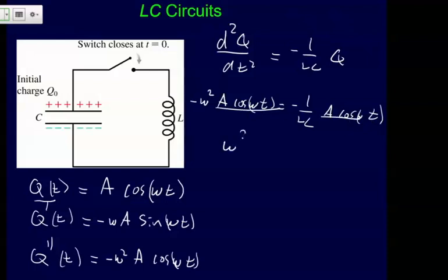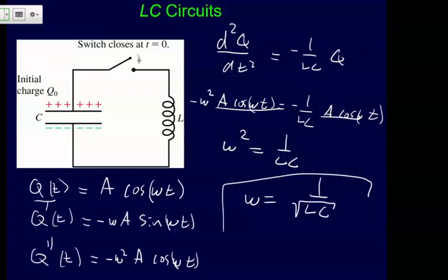And I get this important relationship here. So again, to unpack all this stuff, because this is kind of mathy, we're starting with Kirchhoff's rule. We showed that basically the charge is going to be an oscillatory function. It's going to be a sine function. It's going to oscillate. And better than that, we found that the oscillation frequency is 1 over radical LC, by going through and doing this here.